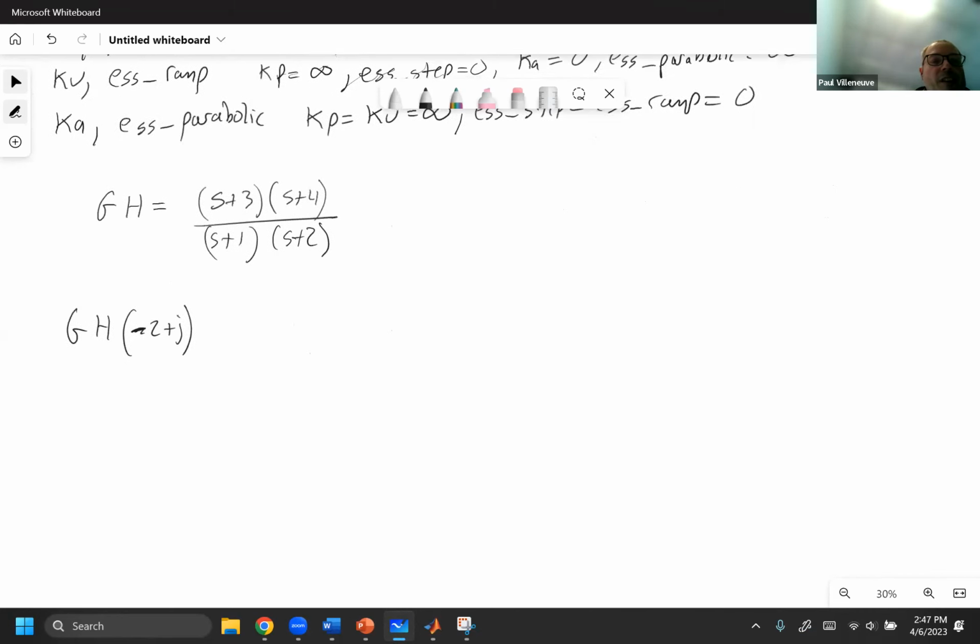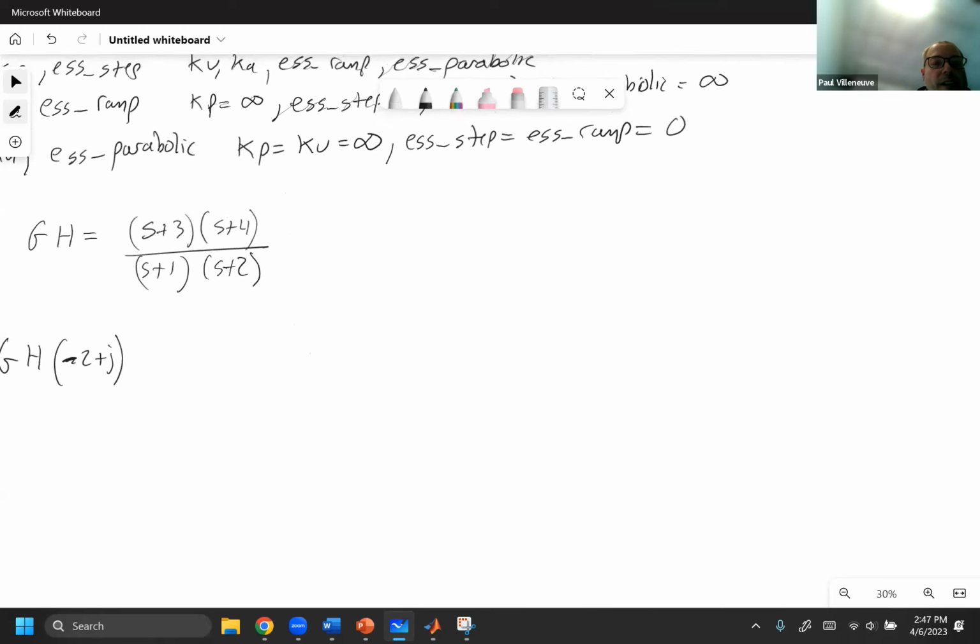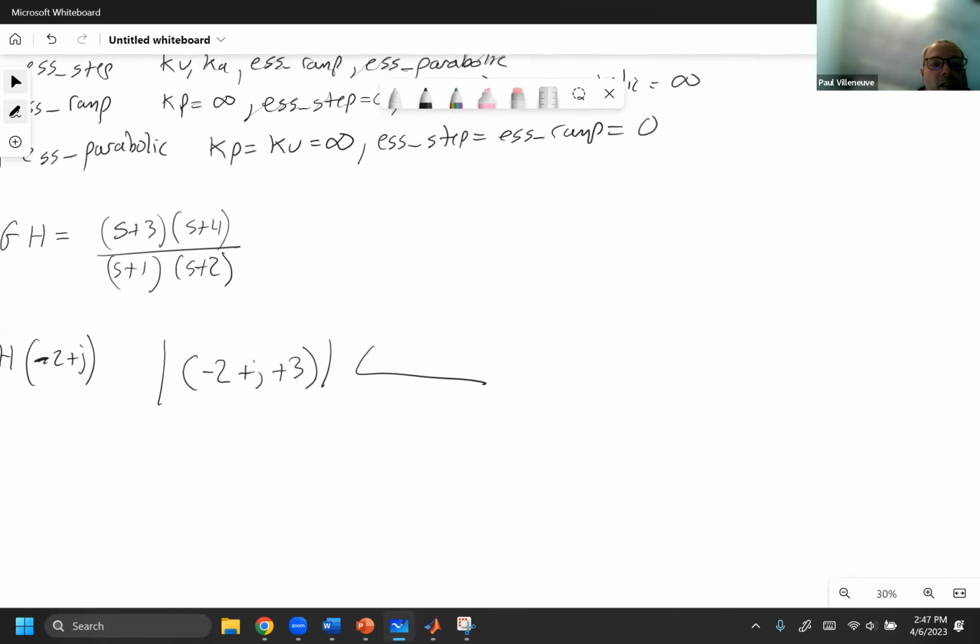So the first thing you need to do is figure out what the magnitude and angle is of S plus 3 when S equals -2 plus J. So what is the magnitude of that? And what is the angle of that? Well, first thing I'm going to do is get the magnitude.